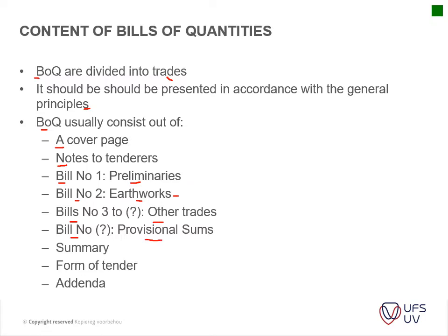You should know at least what a provisional sum is. A provisional sum is something that's allowed. There's a monetary value given for items, usually items like your HVAC, or any mechanical installation where the design is not done when you go out on tender. It's usually done by a specialist contractor, who does a design and install for that item.